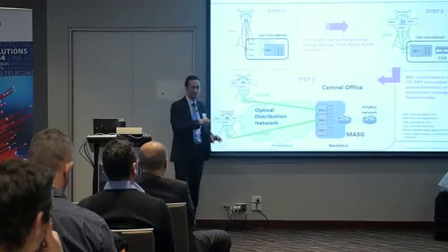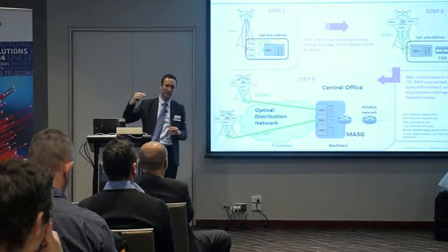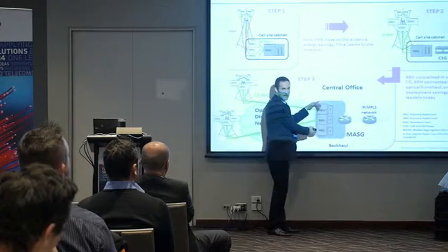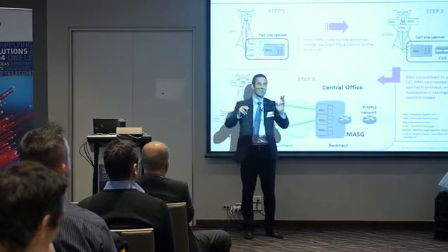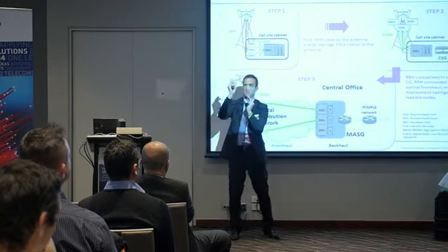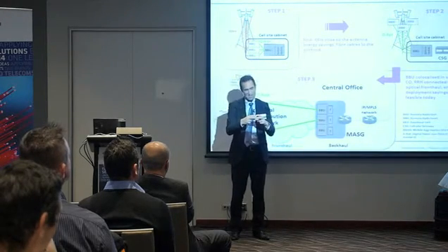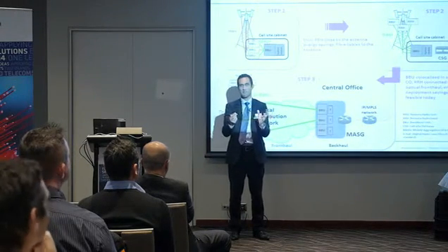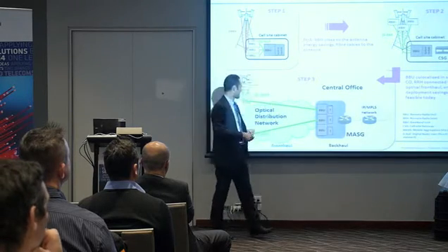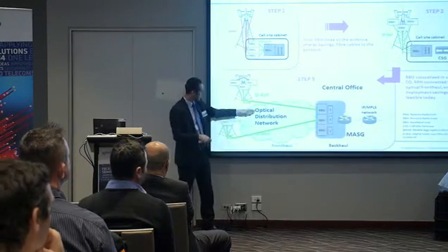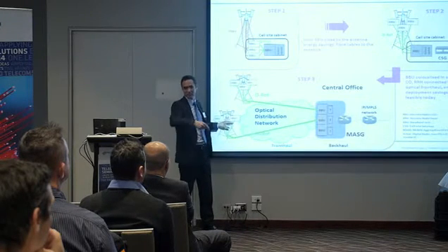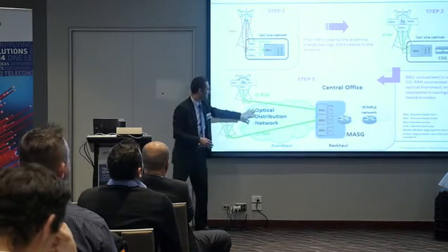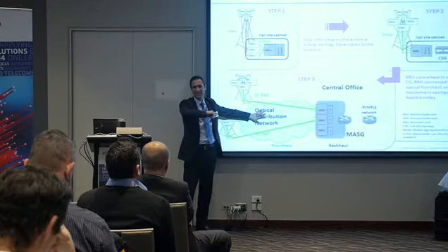And then maybe ultimately, at least they are thinking about it for LTE Advanced or 5G, try and put all the base stations together, so get rid of the model of a base station and antenna, a base station and antenna. Just co-locate, put all the base stations, the baseband units, together in something like a central office, and then distribute over fiber through optical distribution networks the signals toward the remote radio heads. Okay, this is, I would say, next generation because it's complicated.